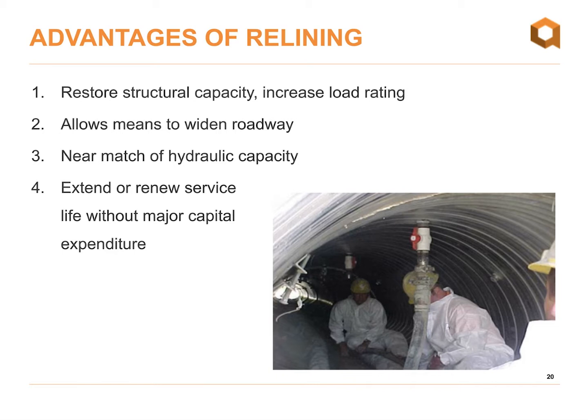Secondly, it allows for a means to widen the roadway, of course. So fairly simple, but we just basically extend the culvert, supply an extra length to allow for widening the roadway. Thirdly, at this point, we can nearly match the hydraulic capacity of the existing structure.